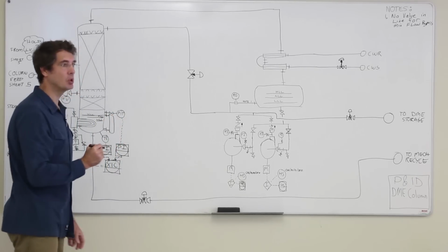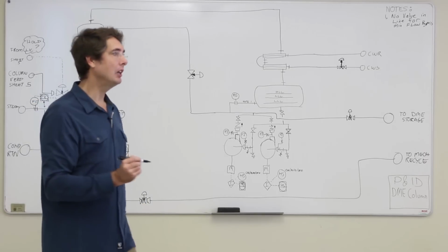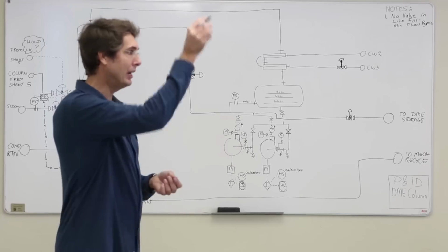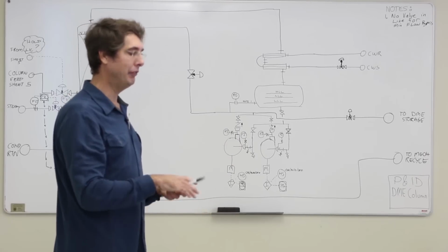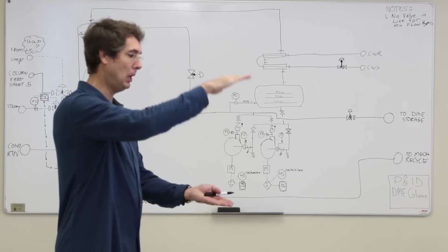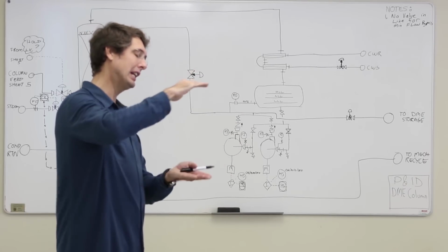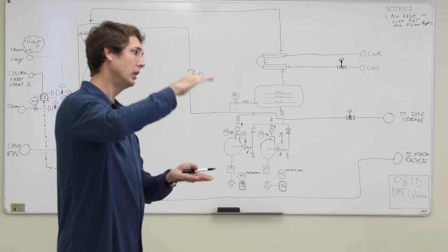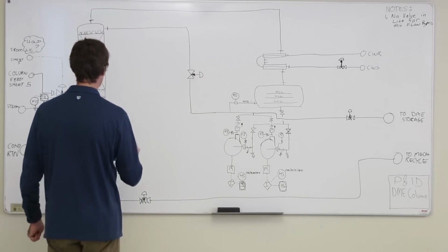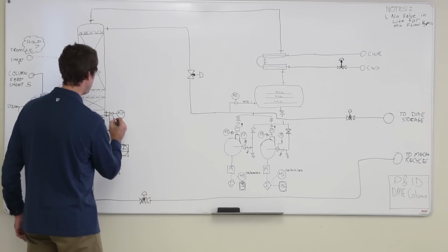What this looks like is a lot like one of the big coffee urns. The big coffee urns have a little sight glass on the side. If you notice when you start draining coffee out of the pot, the sight glass doesn't drop as fast. So it dampens the actual measurement of level.